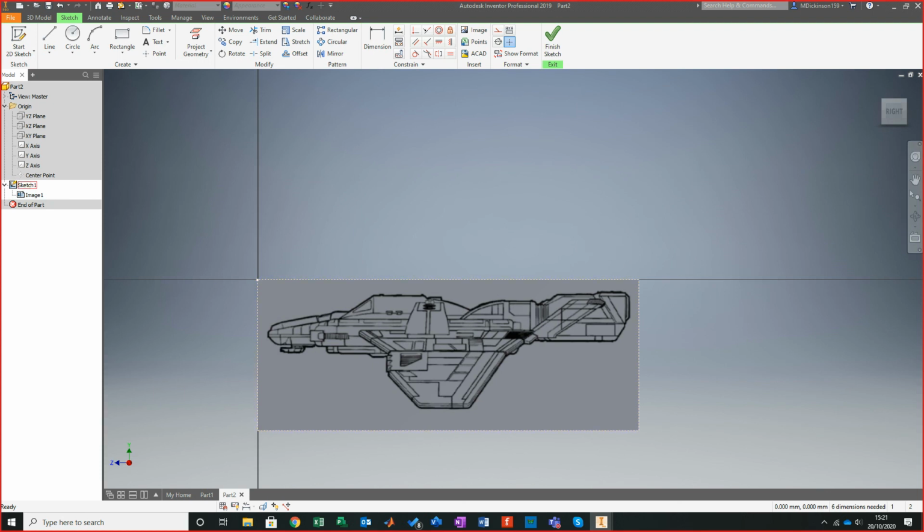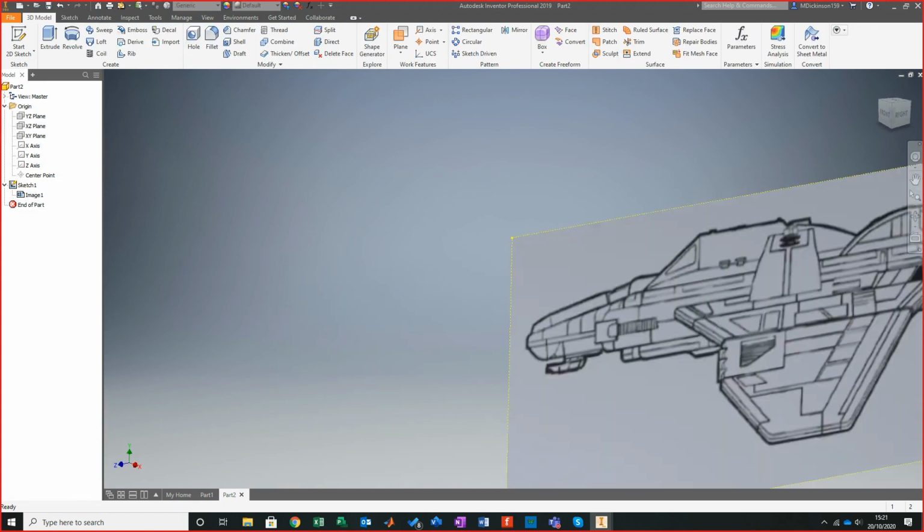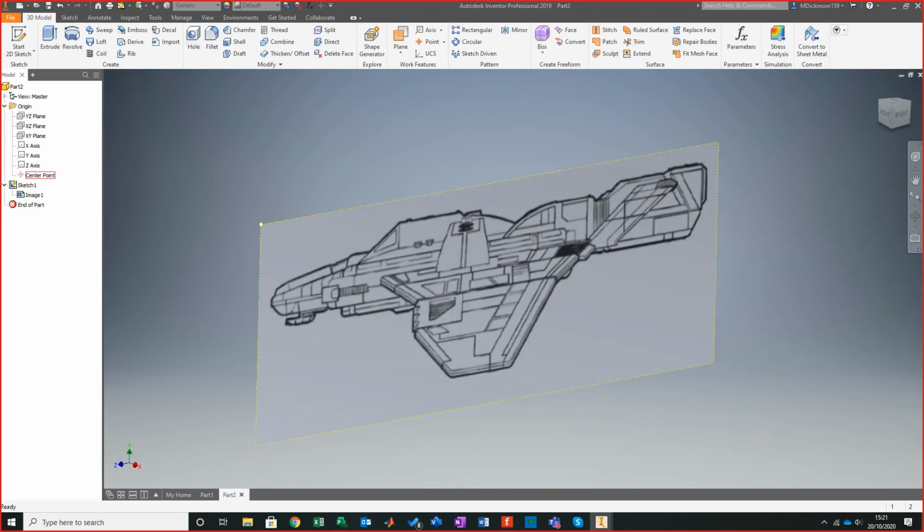I would always recommend turning this into its own entity. So what I mean is, if I just click OK, bring this back, and then just call this side image, I'd always recommend that. It allows you to just have a playground, if you will, of particular places where you can move things around and you don't have to worry with everything else. If you want to properly constrain this to the center, you can draw construction lines onto there and literally move this by constraint. So there's one thing about this that I really do like, that you've got that freedom to be able to do that. It's not a common one that I've personally seen.